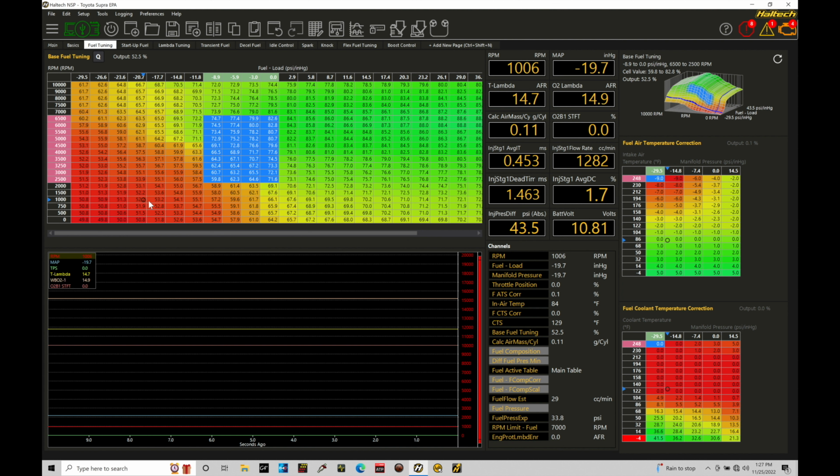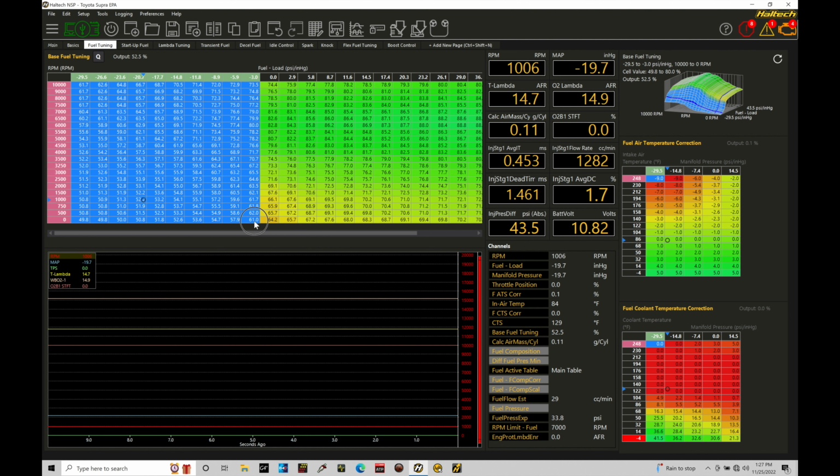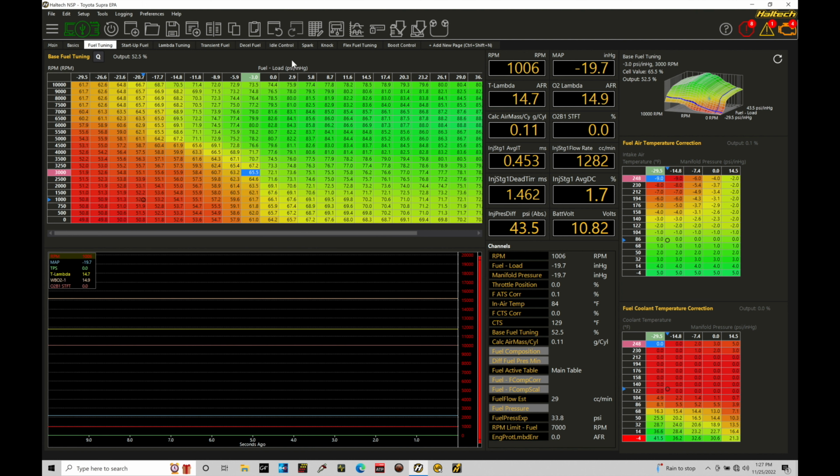Or we might find that we have a combination of ITBs and a big camshaft where we pull very poor vacuum, and as soon as we give it any throttle blade input, we're pretty much at atmospheric or 0 PSI level here. So we have very little usable range. We might not have this much range to map out for idle and part throttle vacuum conditions, but it can be a huge problem. Well, in that situation, we want to tune in something called Alpha-N, and we can switch over our fuel load type instead of MAP pressure to something like throttle position, which allows us to have a direct input for the throttle blade movement to look up our percentage of cylinder filling. We'll talk about how we can switch that here in a little bit.